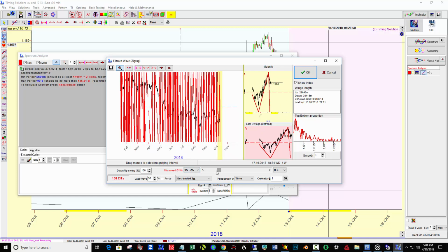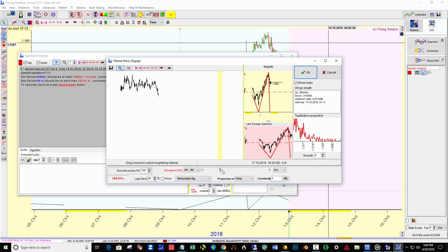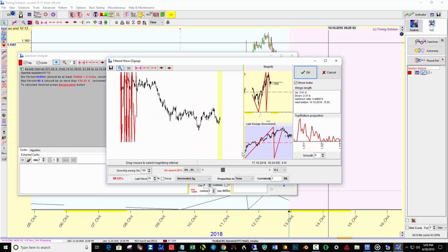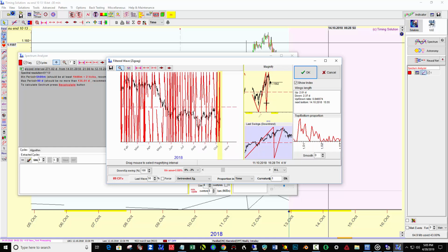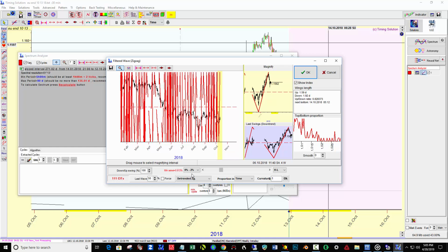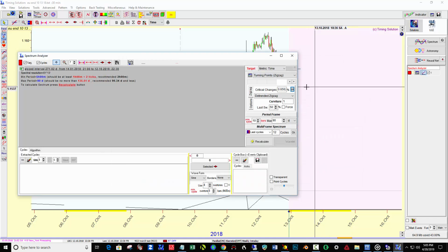And there's a range in here, so that's 0.52 and 0.65 is hanging in there, and by 0.68 it pops into eccentric, more zigzags for some reason. So I'm going to dial it back just to where it crosses that threshold right here. And I'm going to give it 0.65, I think is what I found. 0.638, 0.65. So I'll just say OK to that and put that value in there.